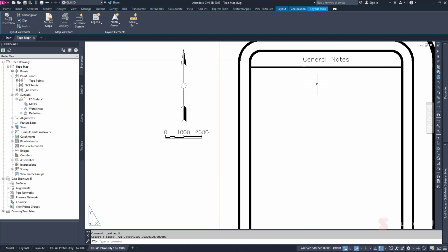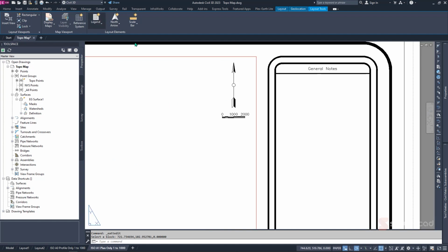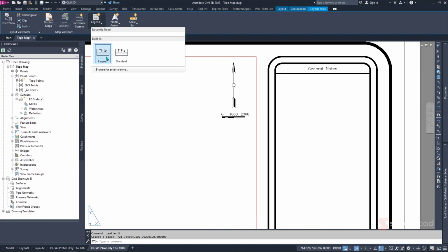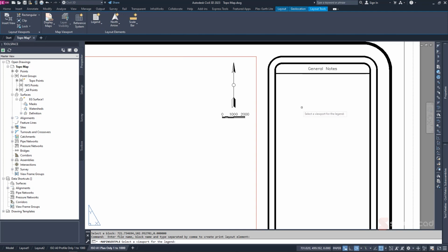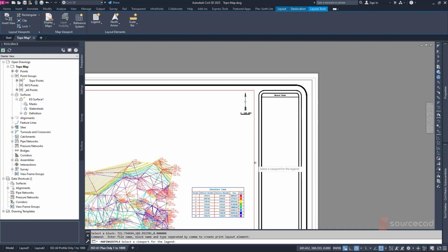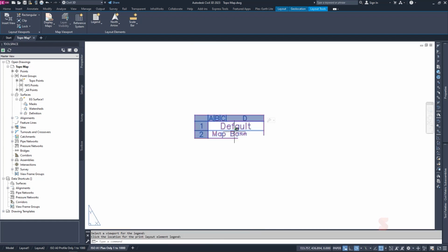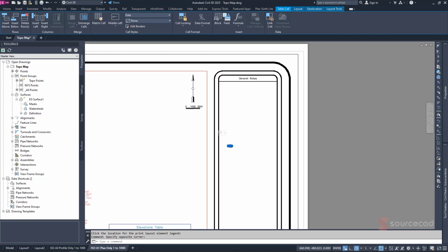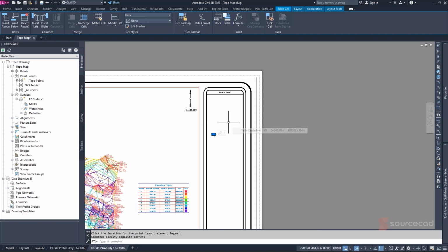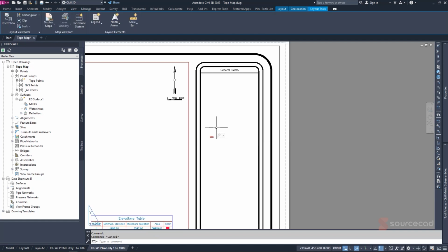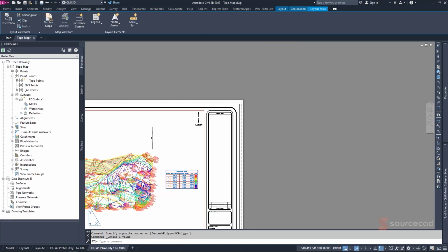You can add your general notes here. You can even add your legend. So in the event that we had not done our legend here, we can now add our specific legend for this viewport. So if we had multiple viewports, we can now specify maybe this is the map base and something of the sort. But for now, we do not have so many things happening. So we can just do away with this one. So select it and delete it, and it will be gone.